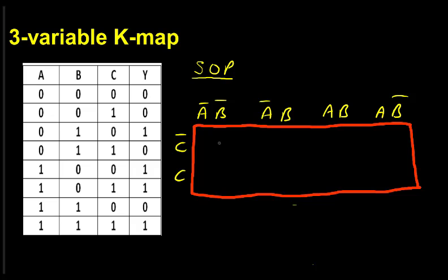Now let us see how to draw the K-map. Okay, because in this, these are the output entries which I have to enter, okay, for the inputs. So I see there are 4 zeros and 4 ones. So let me trace out where the zeros are. The first 0 is at A, B, C, all 0. So this means A bar, B bar, C bar, for which I should get it as 0. So this 0 should come at A bar, B bar, C bar. So I see A bar, B bar, C bar is here. So this 0 comes here. Okay. Then next the other 0.